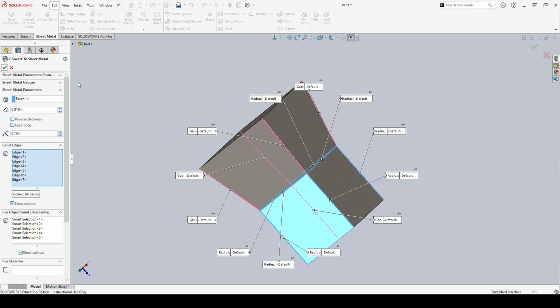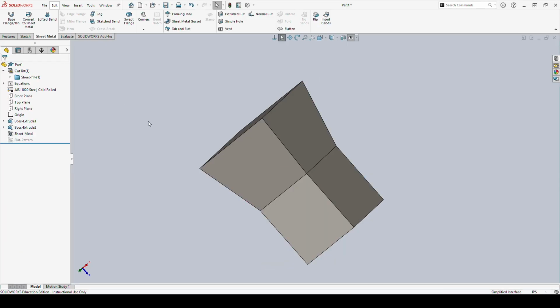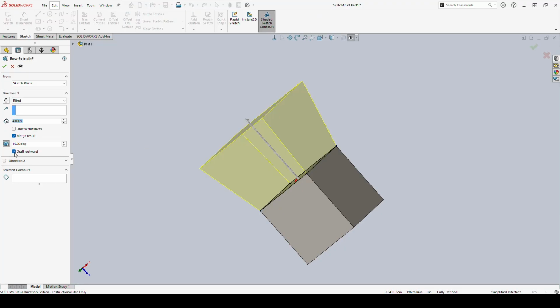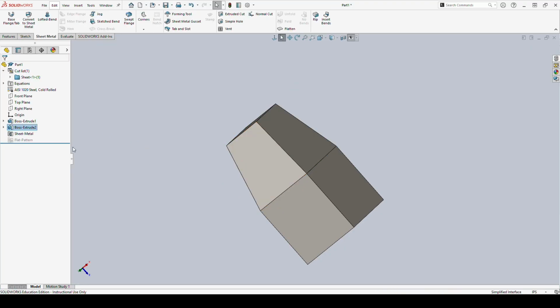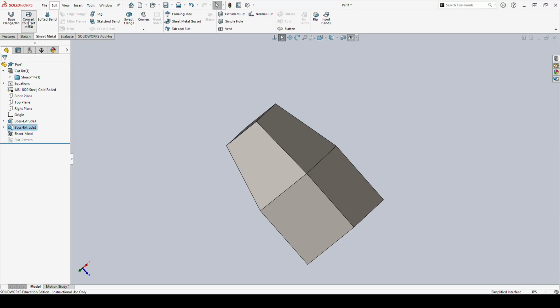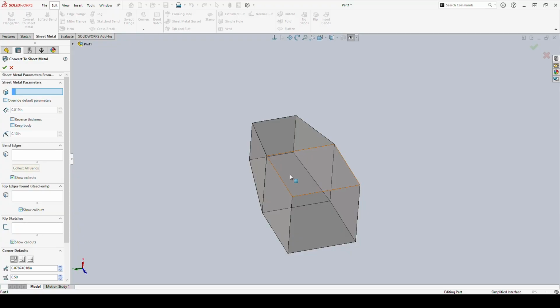So continuing on with this, I go to select. It's like, no, you can't do that. Well, let's go ahead and try changing a couple things. So we can see it, let's go ahead and flip the direction. So my vent is now getting skinnier. Can I make it now? So I'm going to convert to sheet metal. I can click through everything, and it's actually going to let me make it.